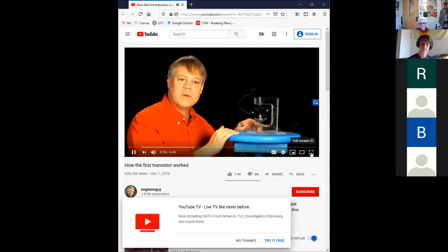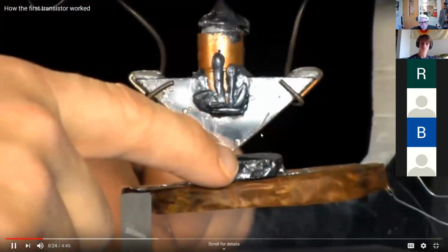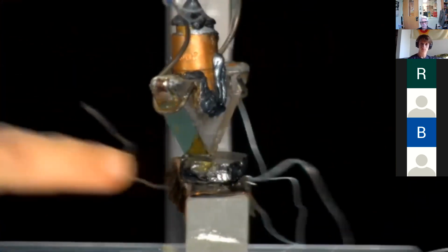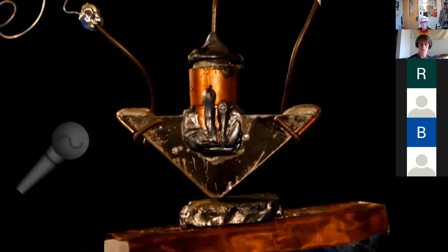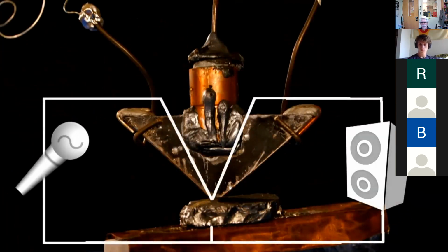All right. In 1947, Walter Brattain at Bell Labs fashioned a plastic set, a chunk of germanium, and a plastic triangle. On each side of the plastic triangle, there's gold foil. And then on top there's a spring which presses the apex of the triangle into the germanium. That's why it's called a point contact transistor. Now here's what Bardeen and Brattain actually did with this device. On December 23rd, 1947, they hooked up a microphone to the left side and an oscilloscope to the right side. As they spoke into the microphone, you could see the voice signal being amplified.